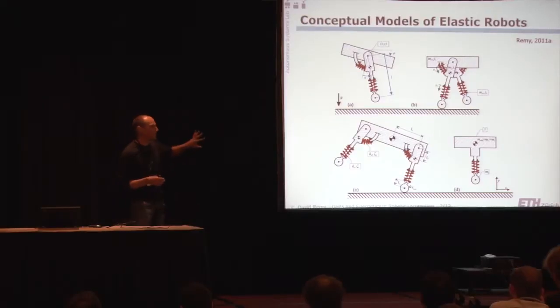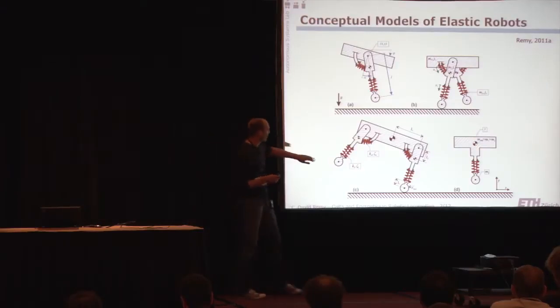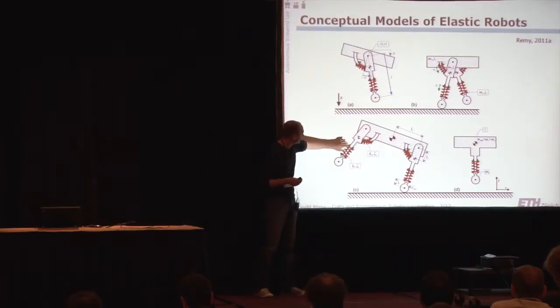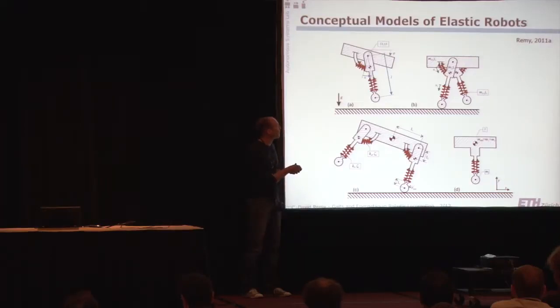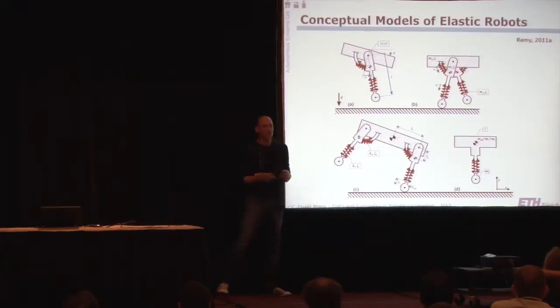So we have distributed masses, that means we have collision losses. We have damping in the springs, that means we do not have perfect springs. There's the possibility to include a motor model in these. And they're all driven by series elastic actuators. So basically the motors are moving these discs up here, and then have a spring in between the joint and the motor, and these are basically my control inputs.